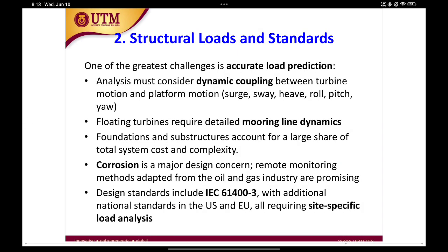Okay, next, structure, load and standard. One of the greatest challenges is accurate load prediction. Analysis must consider the dynamic coupling between turbine motion and platform motion. Okay, so on land, the wind turbine, you don't have to consider lah the surge, sway, pitch, roll, yaw. Okay, I think pitch and yaw, you have to consider lah. Okay, basically not everything you have to consider, it is simple, because the land is steady. But in the sea, the land is not steady lah. That's why you have to consider the dynamic coupling.